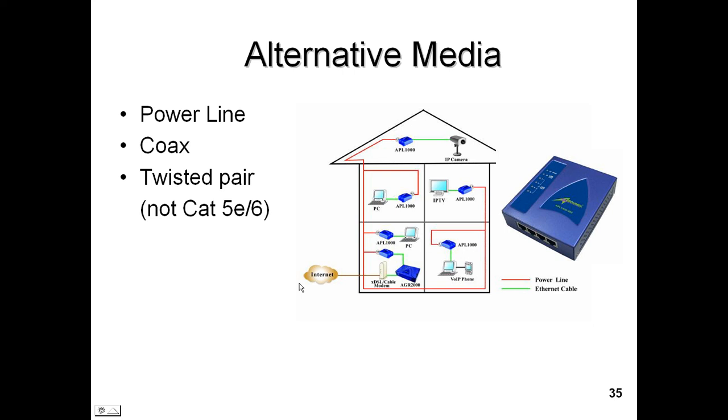You've got an existing coax for an analog camera that was put in 5 years ago, and it runs out there 400 feet. And the customer now says he wants 2 more cameras there. Well, do we want to pull 2 more coaxes? I don't think so. I think what we're going to do is get the transmitters and receivers or transceivers from a company like Veracity or Lan Power, and we're going to use that existing coax.